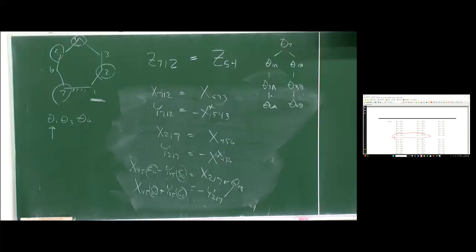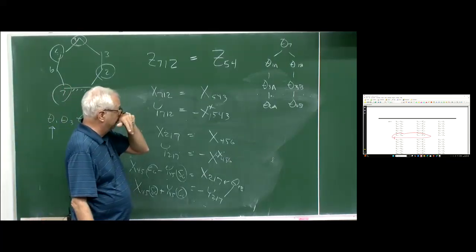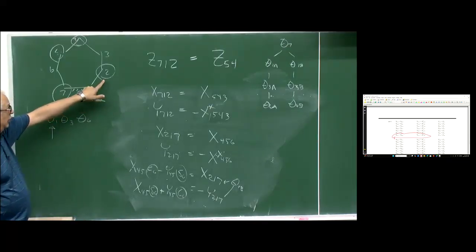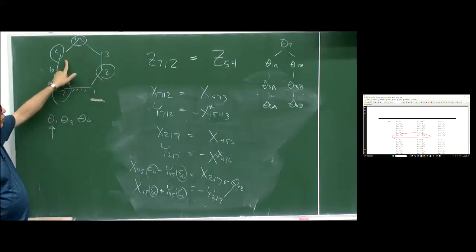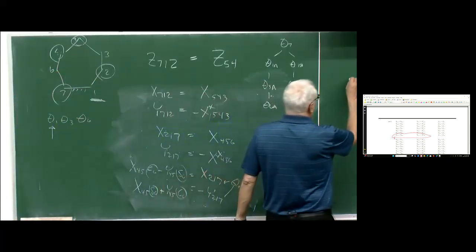So in our problem statement, we've done all we could with the equivalent spherical mechanism, and what's left for us to get are the slider values for the prismatics. That would be the joint offsets S2, S4, and S5. And here we go.